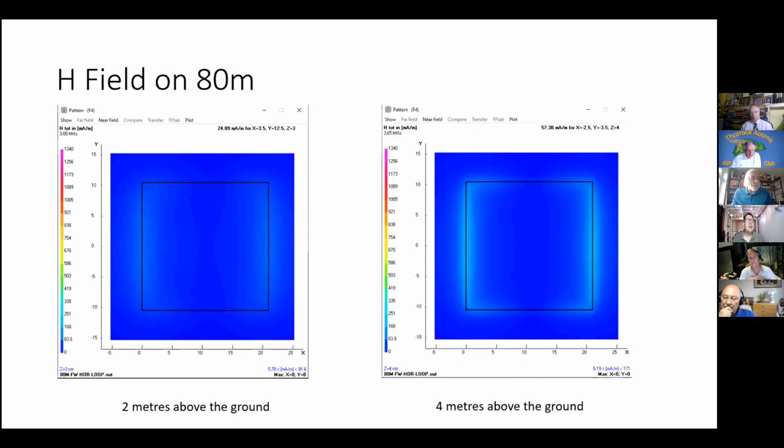First one, you've talked about 160 meters and 80 meters and said approximately 2 meters, very rule of thumb. Will it still be about 2 meters on 40 meters, or does it start to climb rapidly? The 83 volt per meter limit is constant basically from about 1 megahertz to 10 megahertz in ICNIRP, it's basically a power driven limit.